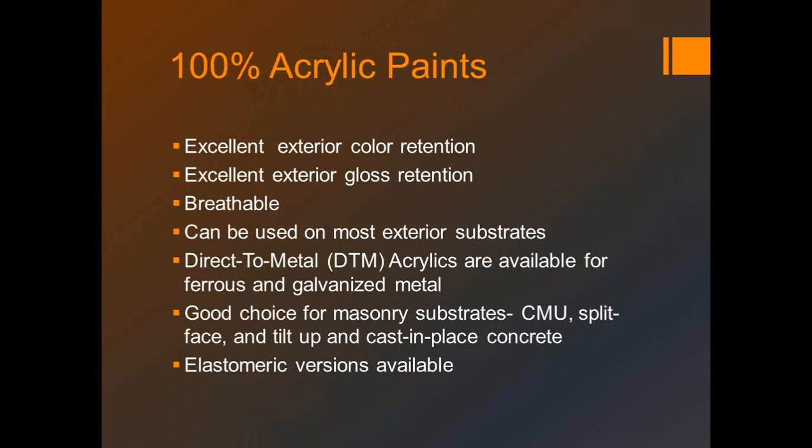But if you have those kind of blisters, leave them alone, let the sun come out, dry the film out, and it will normally rebond to the surface quite nicely, and you'll really never know that you ever had any blisters there. Worst case scenario, if you have a heavy moisture content, they may sag some and you may have to do a little scraping and sanding, but that is an example of that breathability factor.